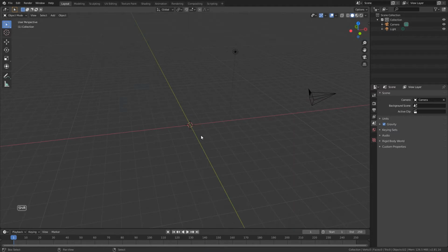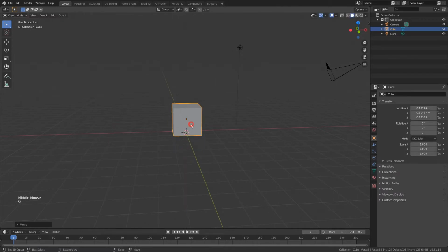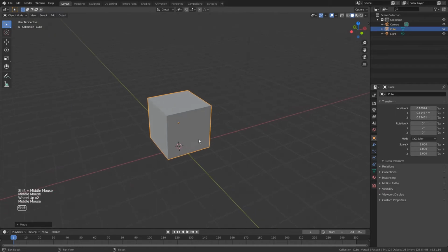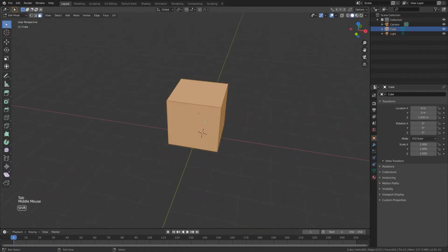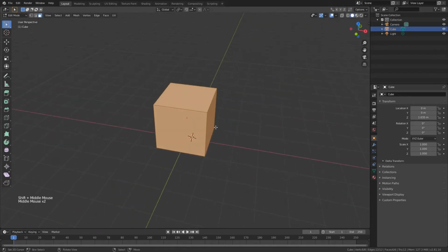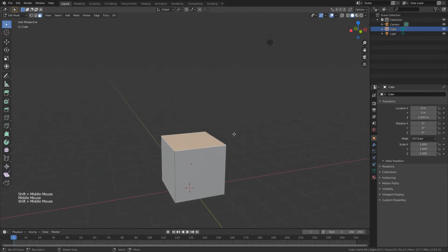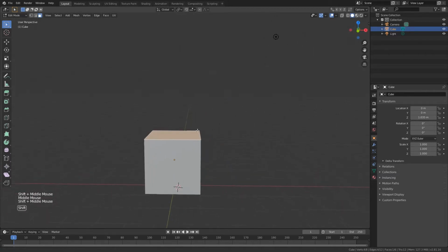Alright, I'm going to create some very basic geometry now, so that you understand how to transform these vertices or edges or create new faces, make your own custom shapes. So I have this box. I'll press tab to go to the edit mode, and press 3 to select faces. Now what I want is to extend this box and create maybe a shape like Tetris.